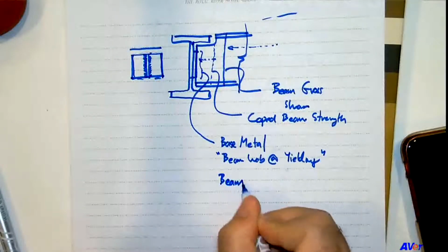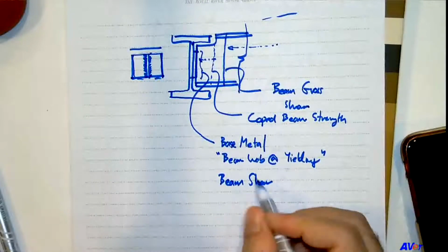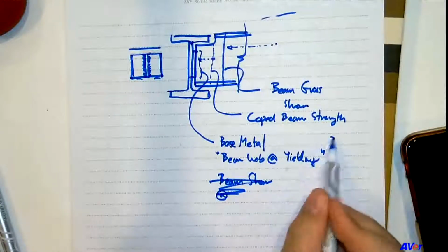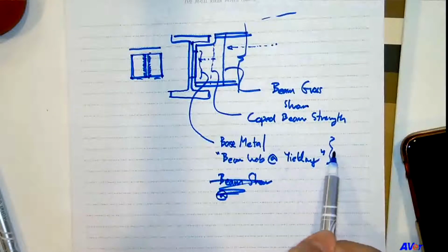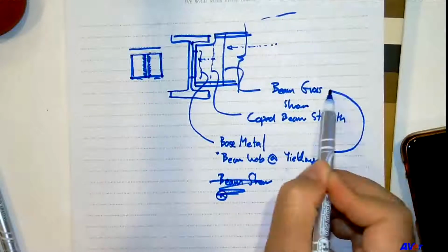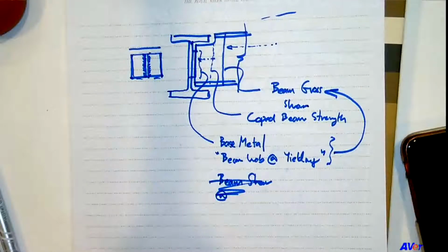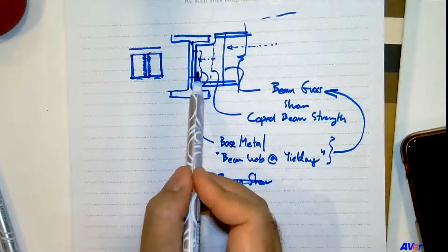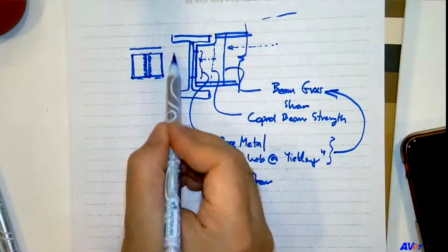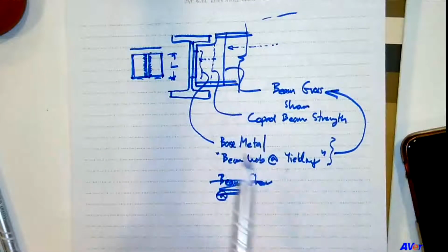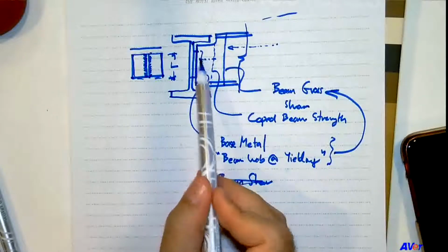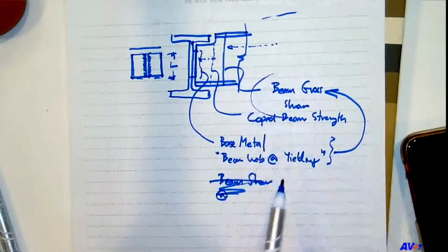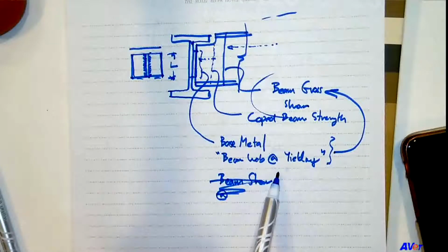beam shear at weld, which is actually it's that one, silly me. This is always smaller than the beam cross shear, right? Because this is where the shear can fail the beam. Under this length alone, so you only need to check the load carrying capacity under shear of the beam with this length. This one will not occur before that one. Right?